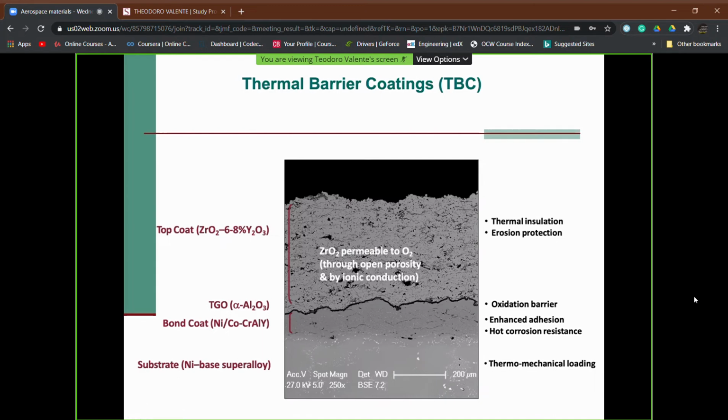I mean that when we put, generally speaking, a ceramic material on a metallic material, think, for example, of putting the top coat directly on the nickel-based superalloys, not discussing now corrosion deterioration but mechanical loads, if we raise the temperature of this system, think the engine is going to work, we will have, with respect to room temperature when the engine is off, a dilatation of the materials, which is directly linked to the thermal expansion coefficient of the material itself.